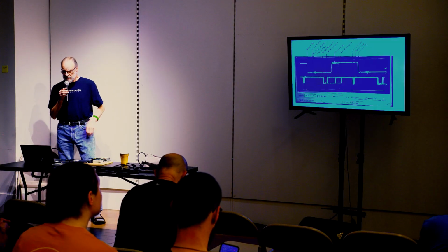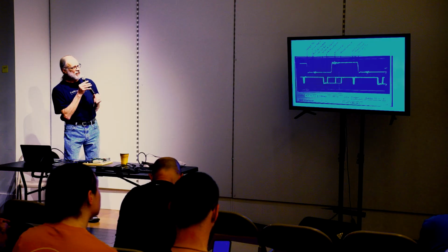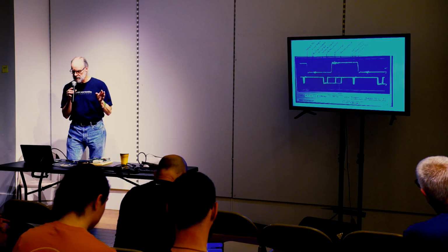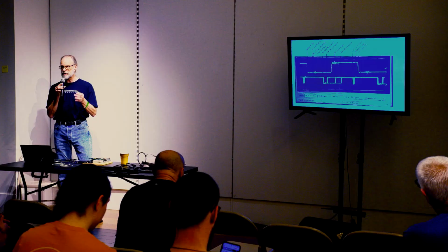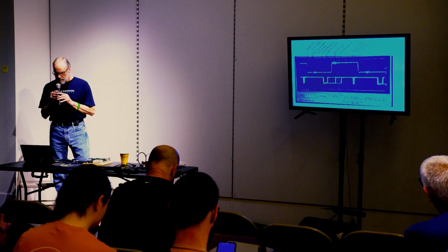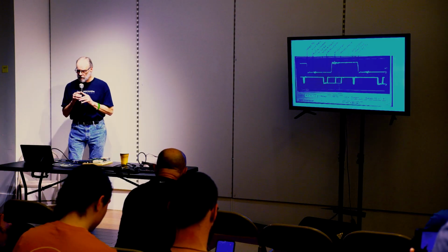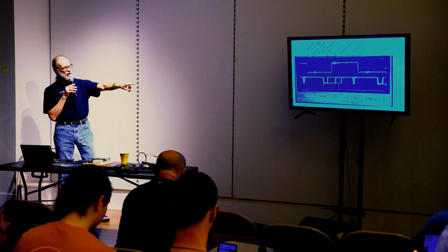So here's a scope view of what was going on, and you can see how the various software operations are being executed in time in relation to that top trace, which is the E-clock. It takes some time to wake up. You can finally see where it samples the data bus. That's where I drive the line low on the bottom trace.